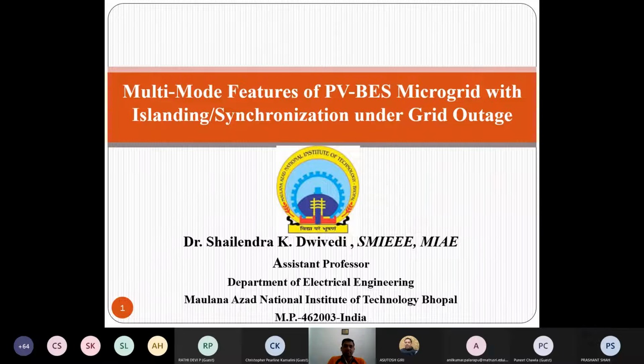Some energy is needed to charge the battery, whenever in standalone mode, suppose PV is not there. So you have a battery energy storage and you discharge this battery energy storage to feed continuous power to the load. As the grid recovers, if the PV energy is sufficient and more than the battery energy storage and the load connected at the microgrid, these two components will consume the energy if the battery is below 80%. So we have to charge the battery as well as supply continuous power to the load. PV will supply the load as well as charge the battery energy storage.